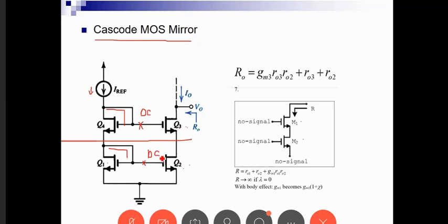So practically speaking, the current mirror is mirroring I reference, because these are sharing the same VOV or the same VGS. The same current that is flowing, because of KCL, in those two transistors here is also flowing in those two transistors because these share the same VGS. There is no other place for the current to flow, so the current in Q2 will flow in Q3.